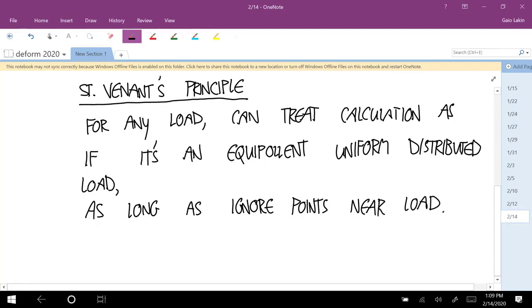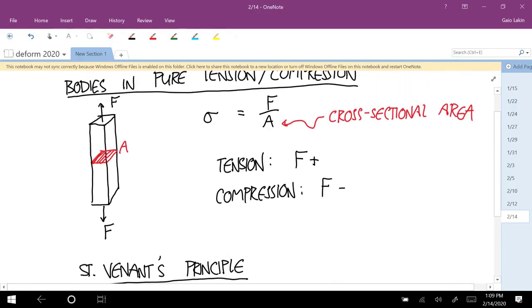Okay, so up here I drew this body that has these point loads applied to it, and what I said here is that the normal stress anywhere along this is equal to this, at any point in that body. Okay, well, I said that this force would make that little point bulge out. And so you can imagine if you really knew what the stresses were as you got close to where that point was applied, things would go haywire up near the top and near the bottom. And as far as we know, things could be going haywire because of that point load all the way through.